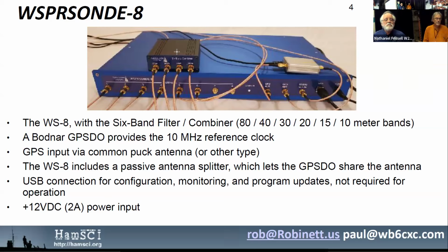And it takes the 6 outputs, and because of the filter topology I use, the combining filters don't really interact with each other very much, so you can combine them into a single output, and that feeds one multi-band antenna. Or you could run separate antennas.